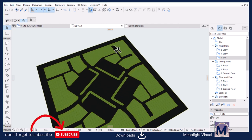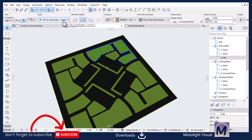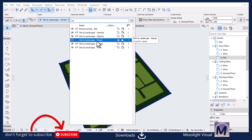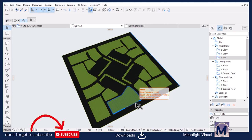Okay, and then I need to assign this a different layer. Oh, they are fine under terrain. I'll leave them under terrain. Perfect. This one should be under road. It says site, landscape, roads. Yeah, because it's important, because we're going to use the graphic override combinations, so it's going to depend more on the layer setting or the layer structure of our file. So yeah, and then we are done with the terrain. We need now to do the massing of the buildings, of the sites, or of the plots.